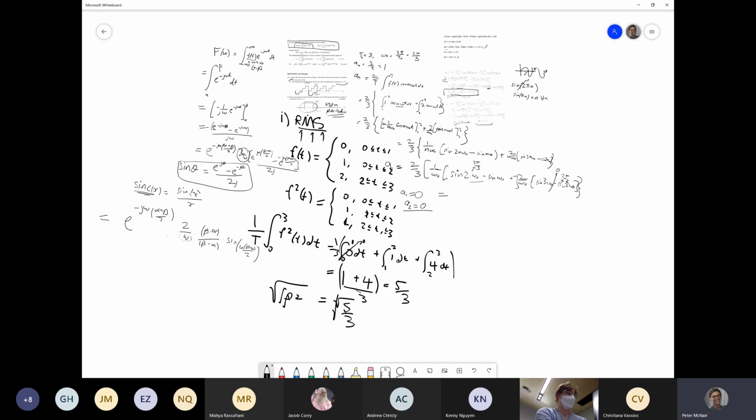So if we essentially put the stuff that we want on the denominator, so we've got omega times beta minus alpha divided by 2, we get e to the minus j on alpha plus beta on 2 times this beta minus alpha times 1 on, well, sine of omega into beta minus alpha on 2 divided by omega into beta minus alpha on 2. So this becomes our sinc.